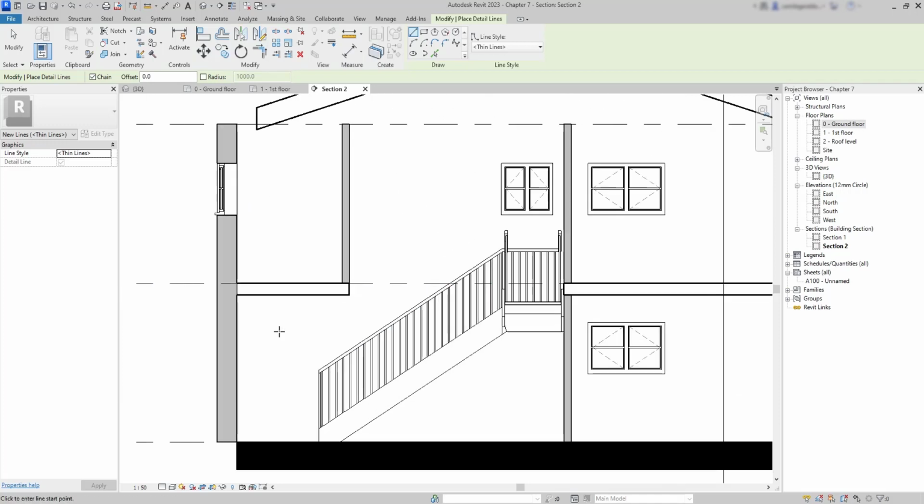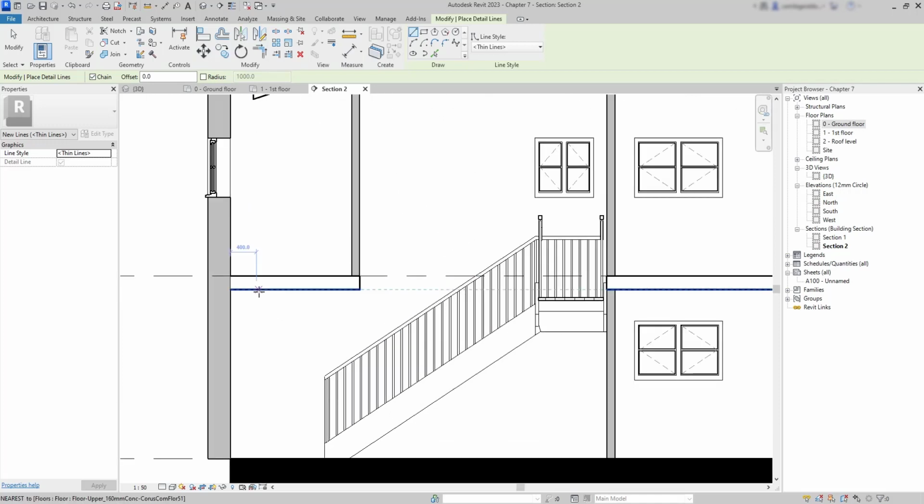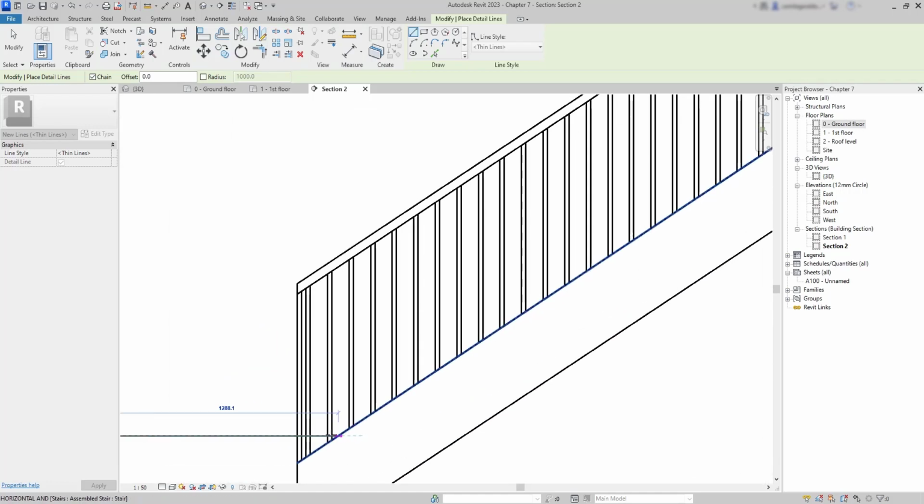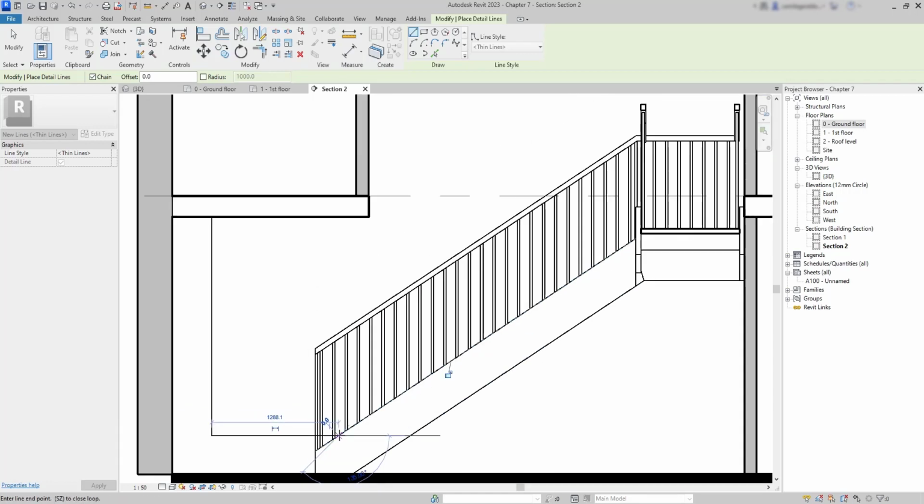Let's start drawing the line from the floor. And I'm going to make the height 2200 mm of length. Then, draw a new line to the right until it matches the exterior support of this stair. Finally, I make another line, this one vertical, to intersect with the floor, and press Escape at the end.